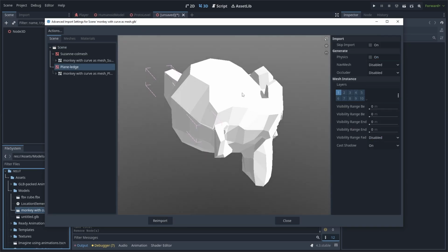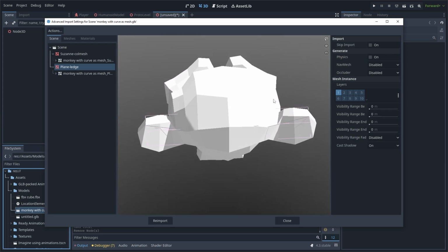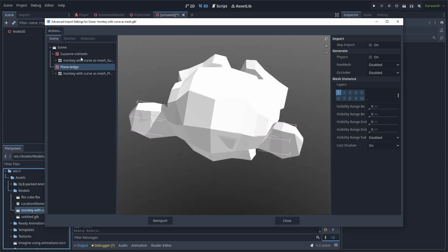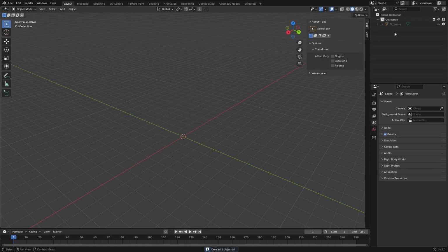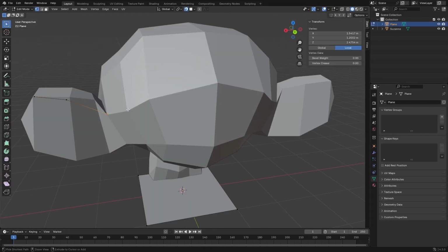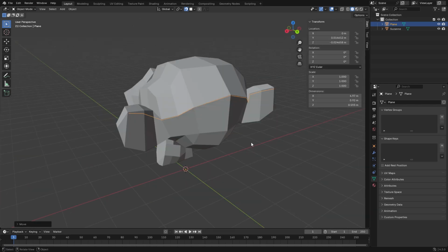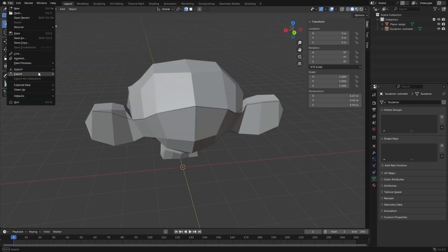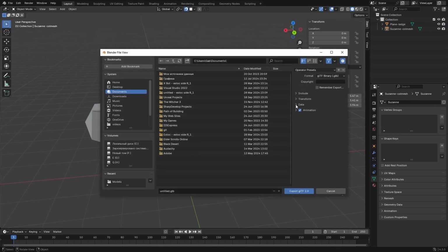Instead, just export these edges as a different mesh and give them names with some postfixes that will power a post-import script for me. For example, let's mark the monkey with a climbable edge. I can enable surface snapping and quickly draw something like this. Now I name this additional mesh the way my conversion map tells me: ledge. You also need to check these checkboxes when exporting. Without them, Godot won't consider our edges a mesh and will ignore them.